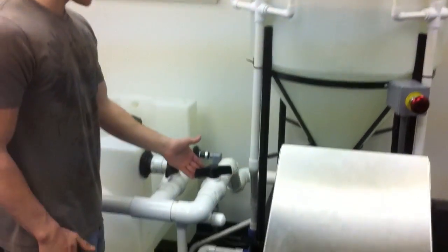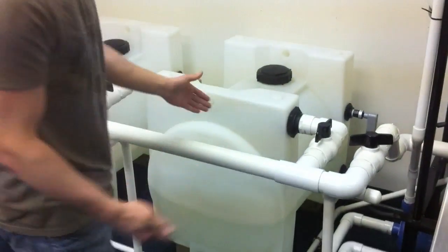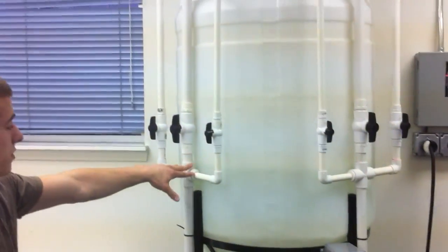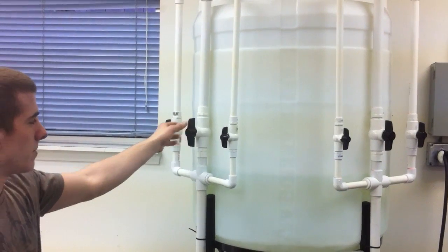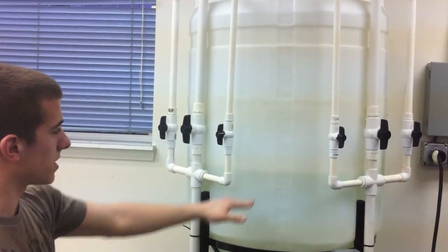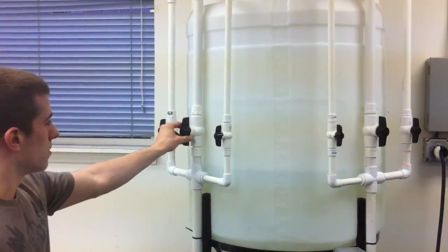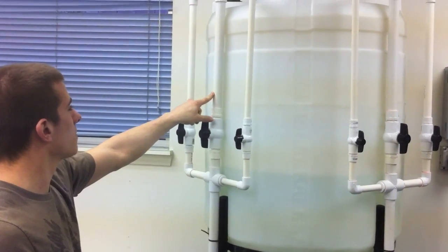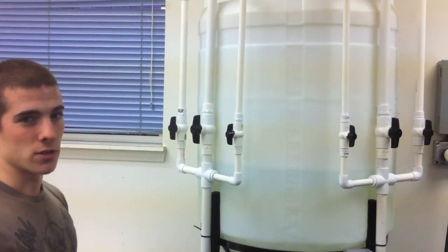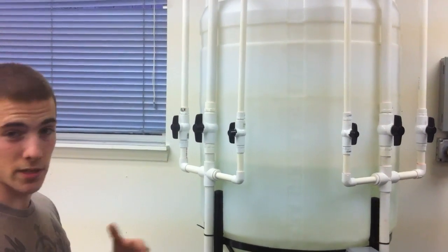This drain valve acts as a limit of how much water is able to escape from the tower tank into the reserve tank. And from the reserve tank, we have the hand valve leading to the pumps, going up through these three pipes here, which act to test the PID loop effectiveness. We can limit it using these three hand valves that go into the tower tank to set the level. Once it reaches this 50 gallons, which it's going to reach in a minute, we're going to limit the flow in from this 1 inch pipe to 3/4 and then 1/2 inch to see at the smallest flow rate if it's still able to keep that set point from our given P, I and D values.